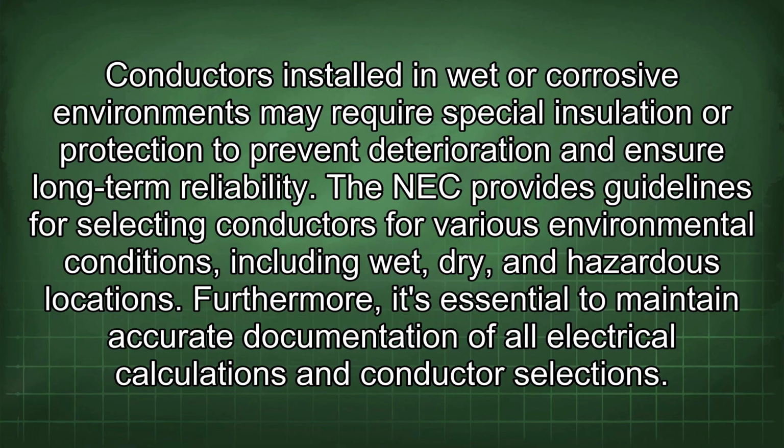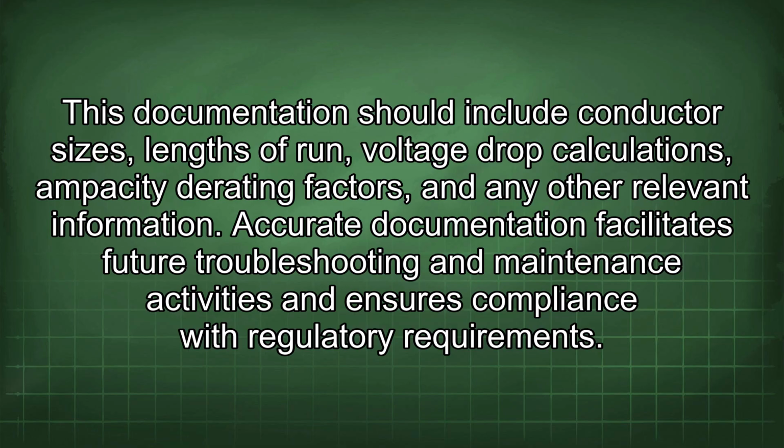Furthermore, it's essential to maintain accurate documentation of all electrical calculations and conductor selections. This documentation should include conductor sizes, lengths of run, voltage drop calculations, ampacity derating factors, and any other relevant information. Accurate documentation facilitates future troubleshooting and maintenance activities and ensures compliance with regulatory requirements.